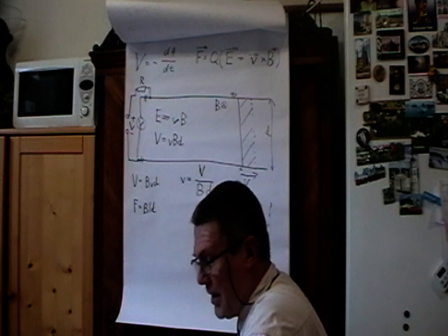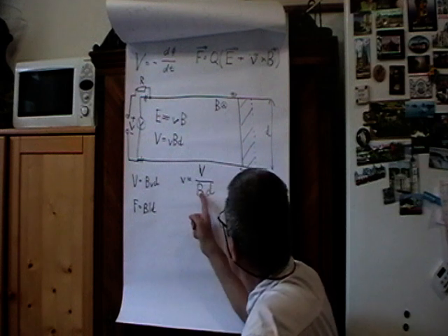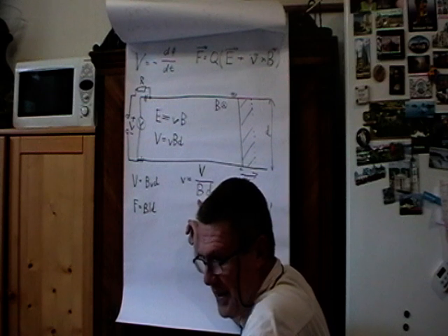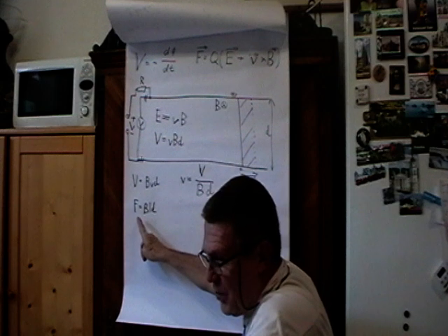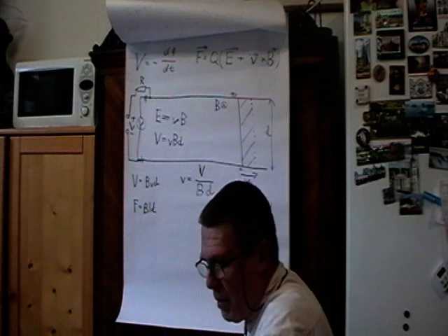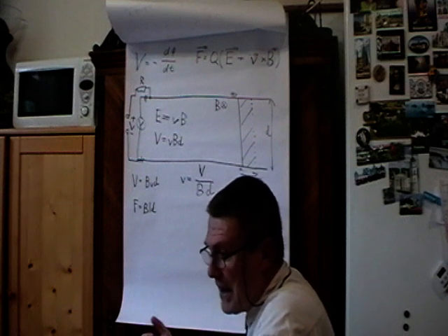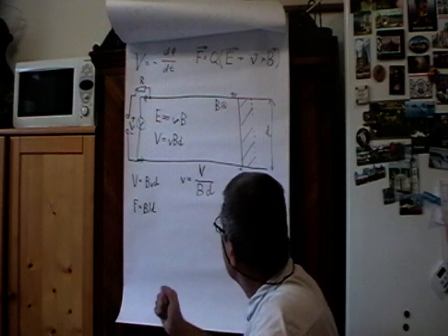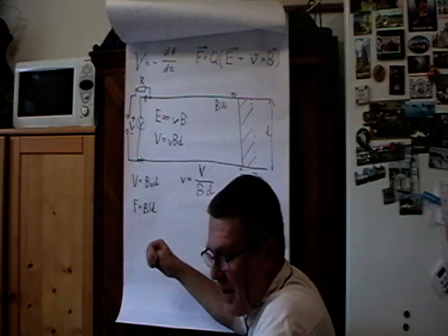If the friction is sufficiently low, that is something like the motor is not fully loaded, then I can ask the sponsor to decrease the magnetic field. If the magnetic field decreases, the force would decrease. In most motors that would mean the torque of the motor would decrease. But if it's not loaded very much, it would work anyway, and therefore as the induced voltage decreases, it would be possible to increase the velocity.